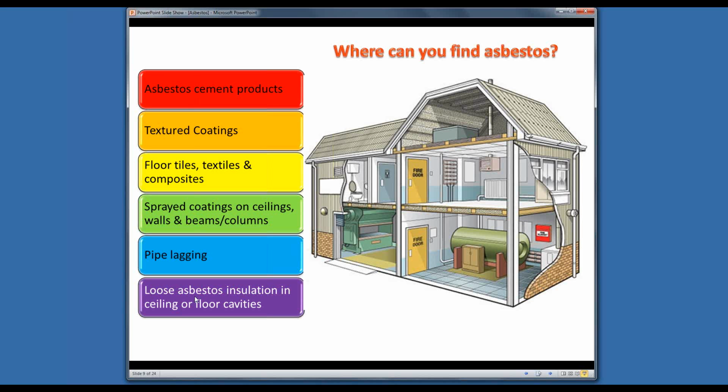The only absolutely sure way to do that is possibly to send the material off for testing, but the issue really is once you encounter anything that you believe may be asbestos during the inspection, it needs to be flagged up and highlighted. Now that can be tricky because if it is something like a floor tile and the floor tiles are not damaged, there's no particular risk. You don't necessarily want to raise a red flag with the client if you're not absolutely sure, but if there is a possibility, it's better to err on the side of caution, because obviously should somebody then decide to lift those floor tiles and damage them in the process, there is the potential for fibres to be released into the atmosphere.